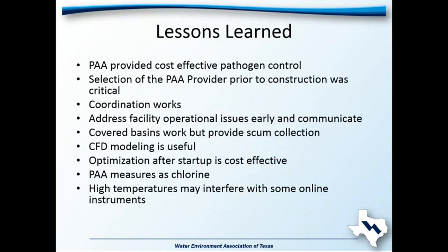And wrapping up, lessons learned for us is that PAA did provide a cost-effective pathogen control for the facility. Selection of the PAA provider prior to construction was very crucial in getting this done. Coordination works. We were meeting early and often with the peracetic acid supplier, the contractors, the plant personnel